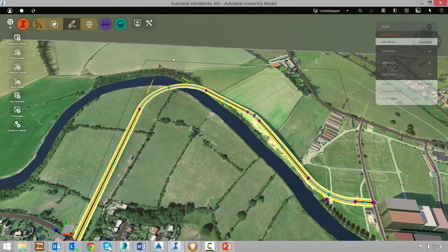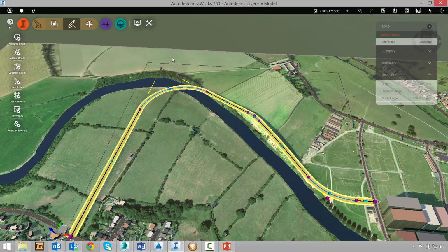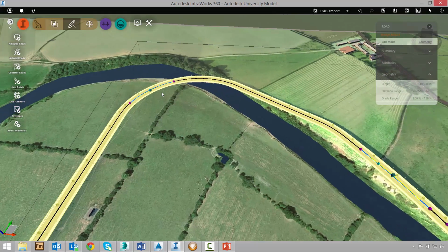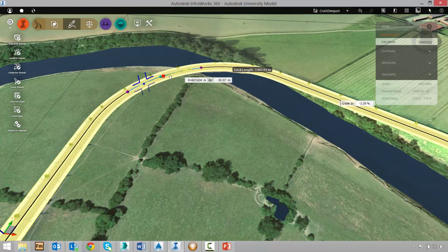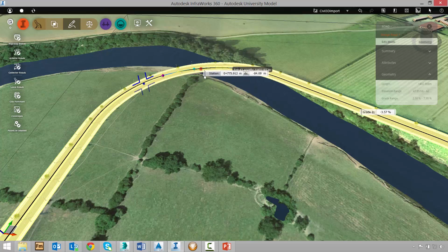And then when I change my model view from a plan view to more than 45 degrees to the profile view, you'll notice the gizmos change. That's because it's changed to vertical gizmos. And so this gizmo right here, that's a vertical curve or vertical intersection. I can move it only in one direction. So if I select it and I start moving it to the right or left, it's only going to change the station of that PVI.